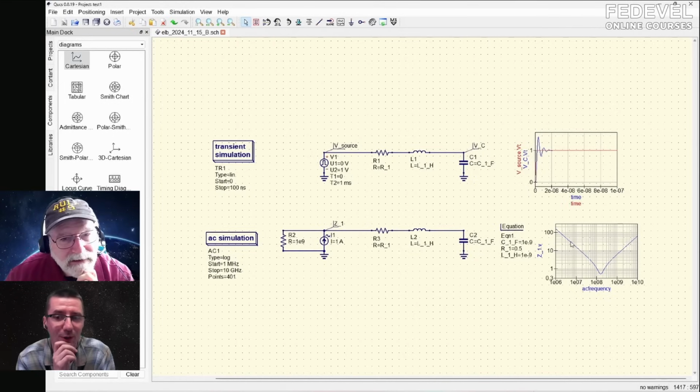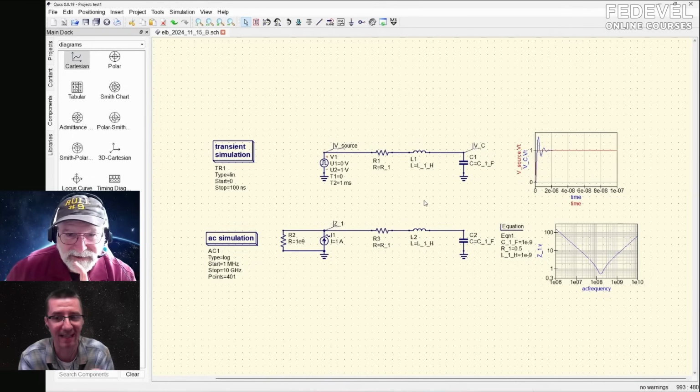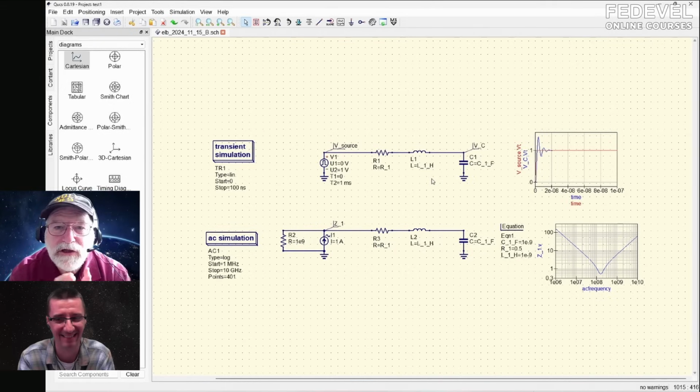And now we would like to go more practical. So we did this circuit, and how this can be applied to PCB layout is that PCB tracks are inductance and capacitance. So let's do some kind of PCB track. I'll do one caveat to that. Thinking about a PCB trace as an inductor and a capacitor is an approximation, a low frequency approximation. In reality, the interconnect behaves like a transmission line.